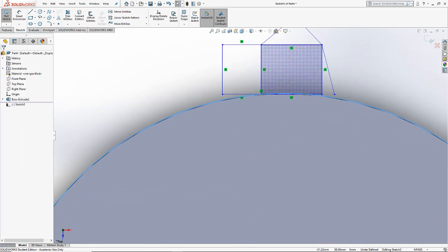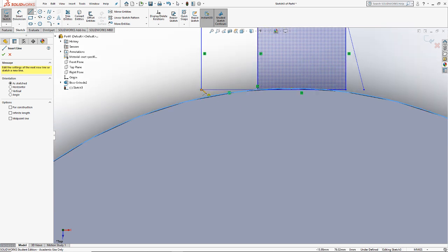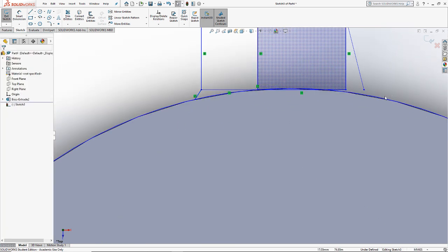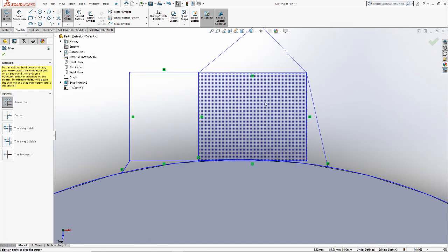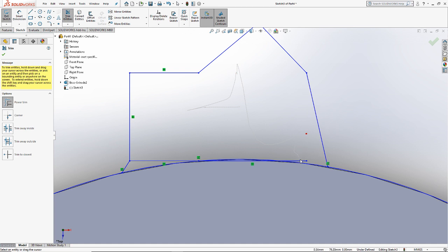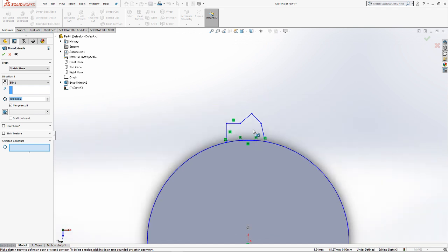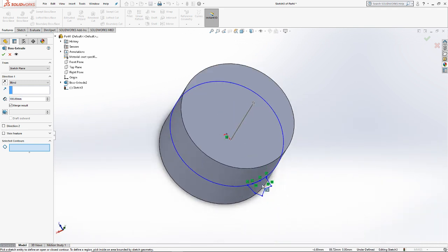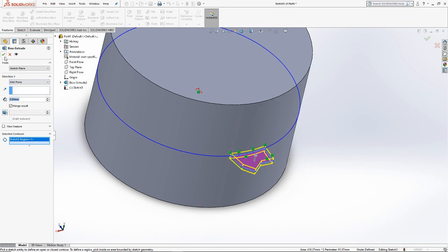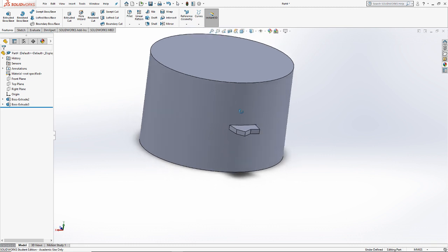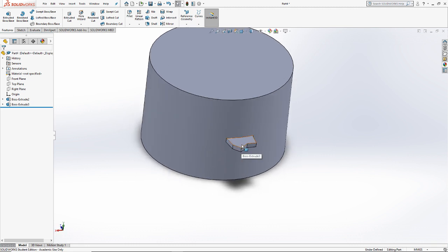So if I had some feature that I had created painstakingly and I didn't want to have to repeat myself, I can recognize opportunities to incorporate rotational symmetry, just like we had earlier with our previous extrusion. So maybe some arbitrary shape that looks like this. Let's say that I wanted this one feature to be patterned around the cylinder. I can use a circular pattern for that.